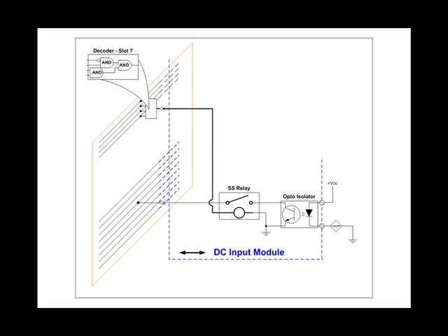When the processor reaches that phase in its sequence where the image of each input module is to be collected and stored in the controller's memory, the processor will then activate one slot at a time, read in the 16 bits from the backplane into a word in memory associated with that slot. Then it deactivates that slot and activates the next slot that contains an input card, and it does this sequentially in numerical order. Okay, so the slots are activated in order.